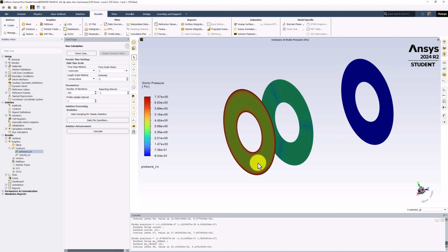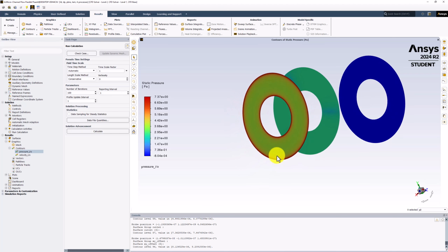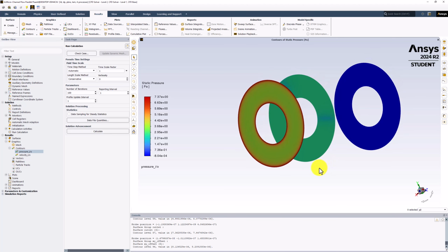On the inlet, we can see that the pressure is nearly constant as well, with the small high pressure area near the edges. This is consistent with expectations for general pipe flow, with the discrepancies being small errors along the edges that will shrink with mesh refinement.